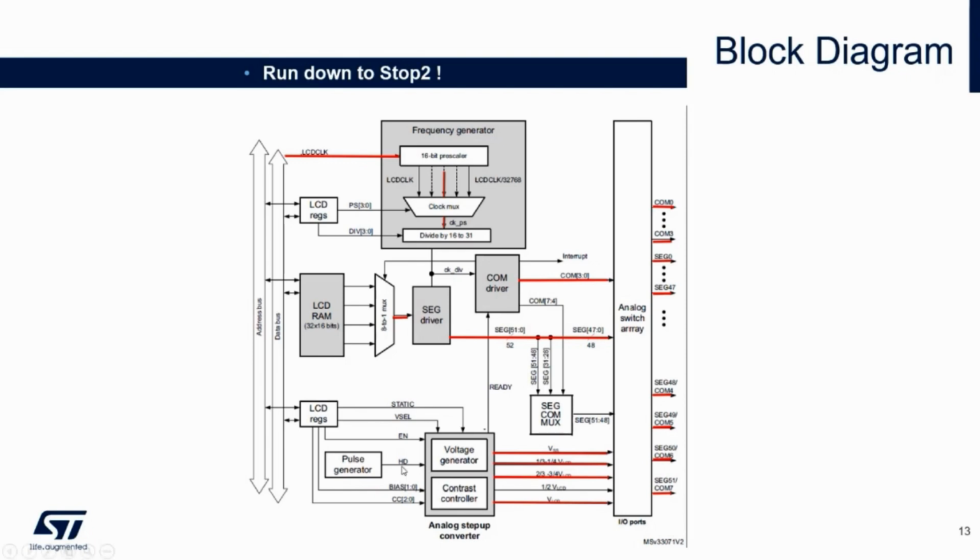You also have several additional subtleties inside the LCD driver that allow to temporarily have a high drive when you have some voltage change on your segments and COM signals, in order to improve the contrast of the LCD, even in a low power mode. Everything is described in the reference manual, so I will not dig more into this because time is running.